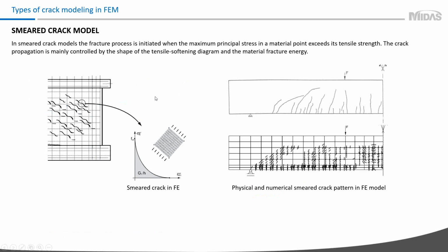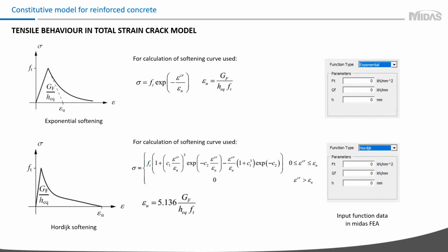On this slide, you can see the uniaxial stress-strain diagram for concrete tension that is recommended for finite element simulation. It's preferred to use an exponential softening type diagram. According to this diagram, during tensioning, the concrete has linear behavior up to the limited tensile strength, and after that peak begins crack opening and the finite element stiffness is reduced.